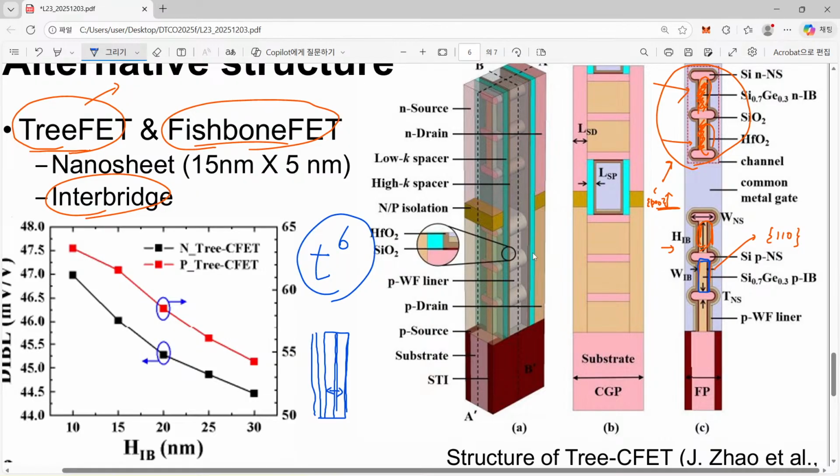So if, for example, we introduce a 2 times thinner FinFET layer, then it is expected that you have about 30 times reduction of hole mobility or electron mobility, which is not acceptable at all. So that's the reason why we need to keep the fin thickness in a reasonable range. So now you understand the main weakness of this approach.